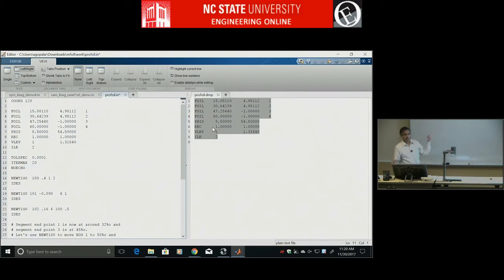Because it's already there and you're saying go there, so it will converge. Now you can push it some more. From 50 you can make it go to 60, put that converged solution there, then from 60 you can go to 80, something like that. You make it do little steps by hand, and then once it works, you might find in the process what is making it difficult.